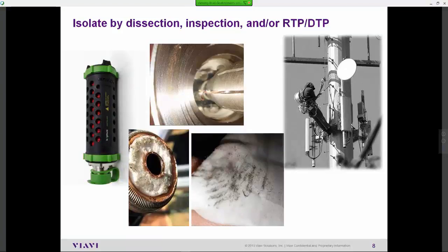For example, where an antenna is at, if you're able to replace that with a PIM-rated load, and your problem, your passive intermod, goes away and you don't see that interference anymore, then you conclude that the interference is in fact either the antenna itself or something actually in front of the antenna.